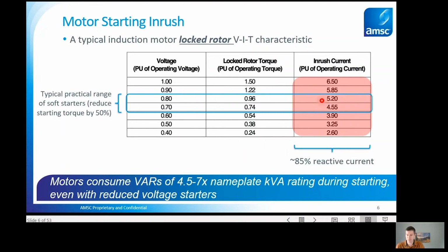So just to recap, we've got a reactive power problem on our hands. It is a fundamental characteristic of the machine. We can't get around it. Reduced voltage soft starting, not going to get us there. So that's why this problem remains challenging to solve.